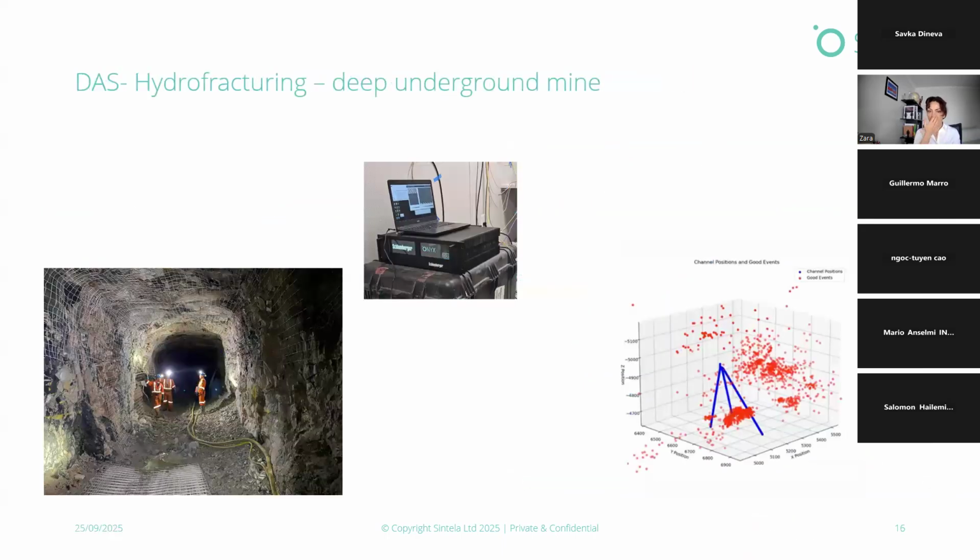And this is another application, again, for DAS and for hydrofracking in a deep underground mine. A lot of deep underground mines, as we go deeper, the stress is becoming a major issue. Sometimes, ahead of mining in a certain area, preconditioning is done, hydrofracking is done to basically create fractures within the rock mass and soften the rock mass. That has been used in addition to geophones in some applications to look at the response of that preconditioning or hydrofracking.